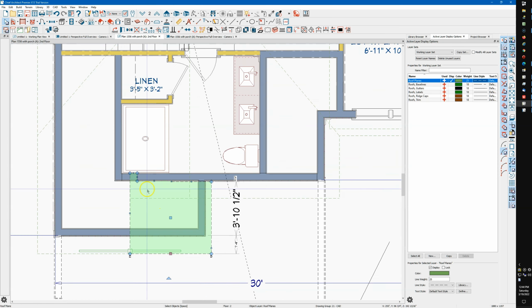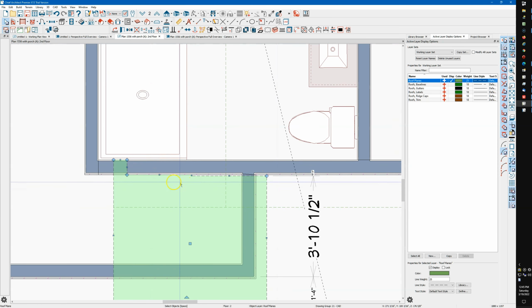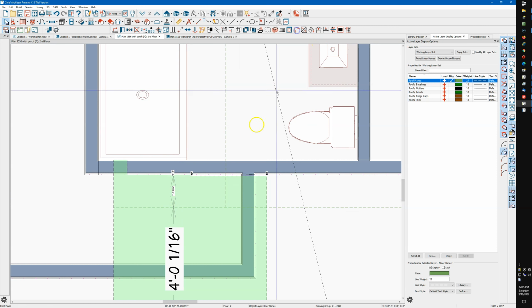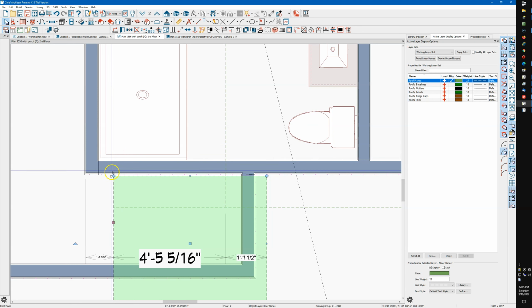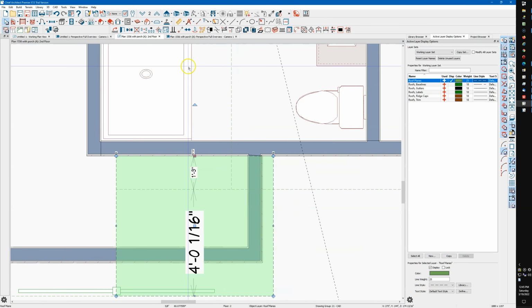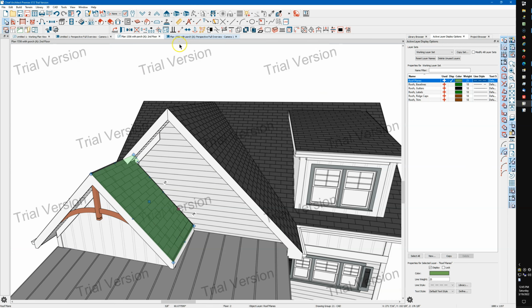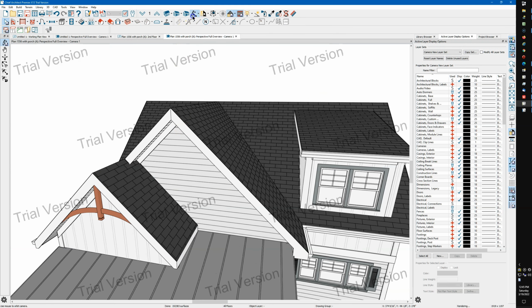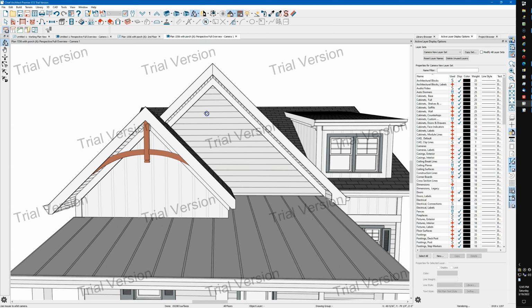So here's that roof plane. And again, you can see it's got all these little breaks in it along here. So I'm going to select that segment there. I'm going to click this intersect join two lines tool. Click over here. And that cleans up this top segment and makes this edge continuous. And then I'm going to push that up against there. And now there's your frieze.